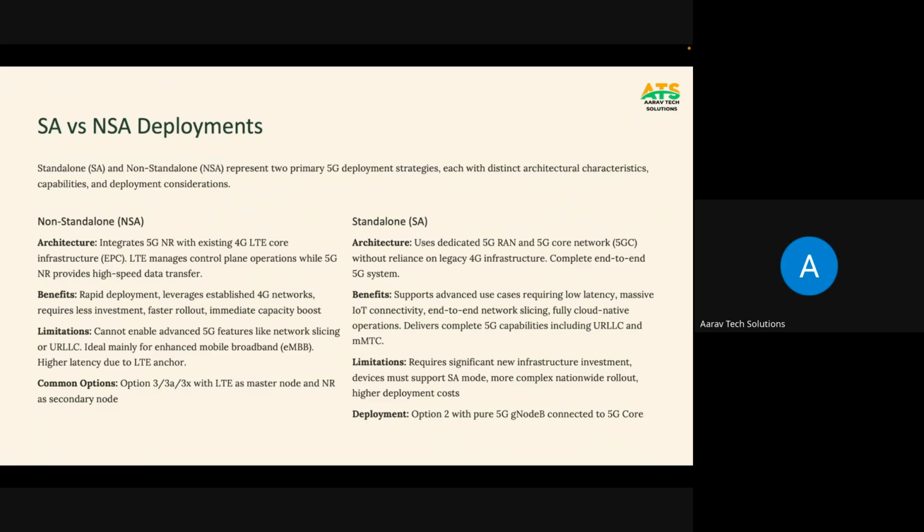Hi, I have a question. I'm sorry, I missed some of it. If the number of subcarriers per radio resource block is fixed like in LTE, what we know is that there are 12 subcarriers per LTE resource block, which means the resource block occupies 180 kilohertz.